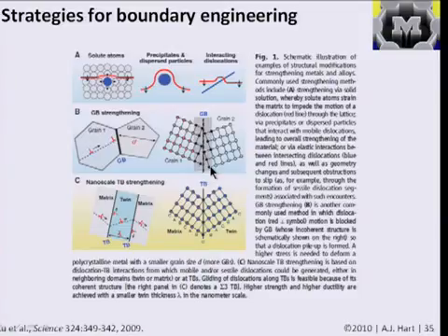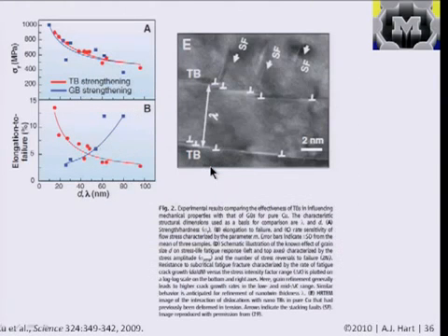And one of the classical things that happens when you decrease grain size in the regime that you strengthen the material, the strength goes up, but also things like the toughness or the amount of deformation you can achieve decreases. For example, the elongation to failure decreases. Essentially it is a more brittle failure. But what they've shown is by putting these different types of grain boundaries, or they're not grain boundaries, they're twin boundaries, in a material, you can actually get more elongation to failure in addition to more strength as the grain